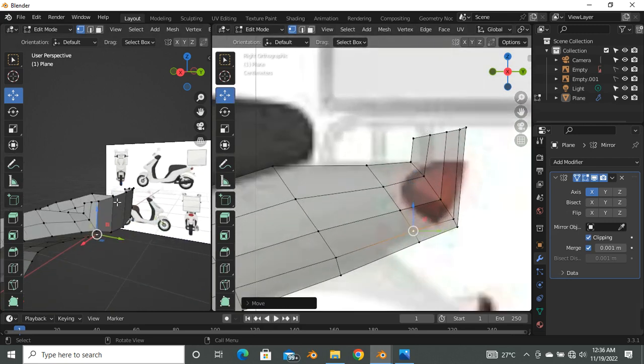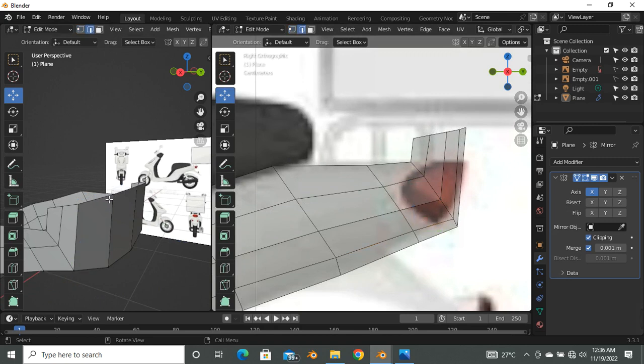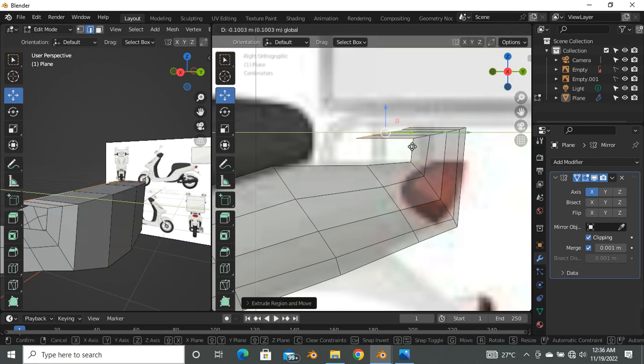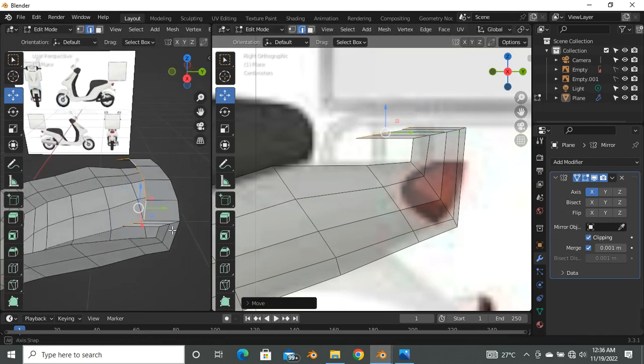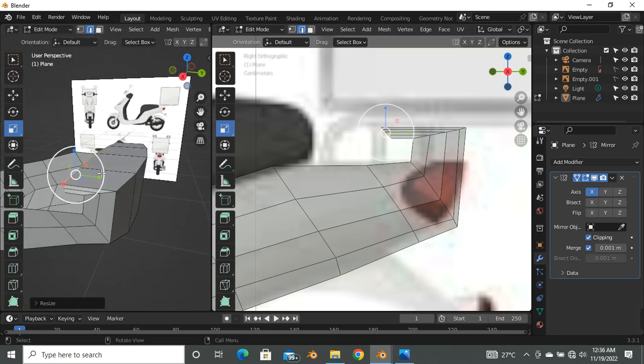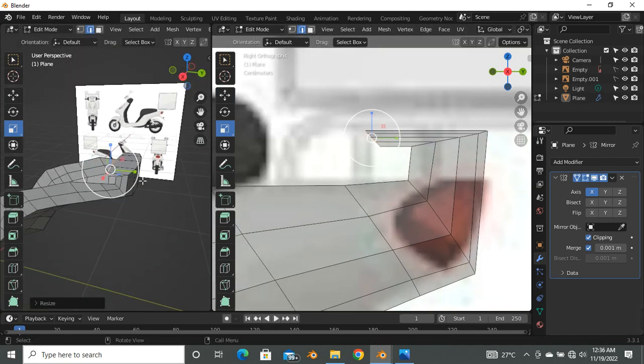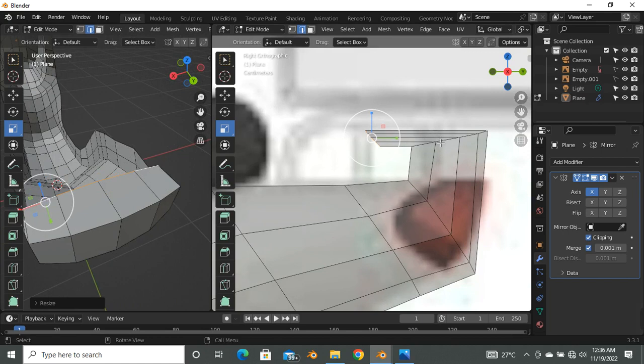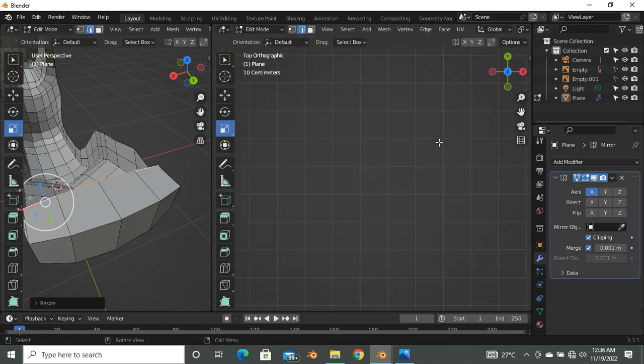I'm going to say 2 for my edge selection, hold Alt, select this edge and say E to extrude, move to this point. So this is what I'm doing now. I'm going to come to my scale tool. I'm going to scale on the Y axis to align that, to make that flat and straight. So I can also say 7 for my top view.